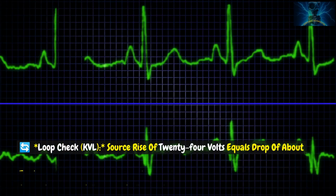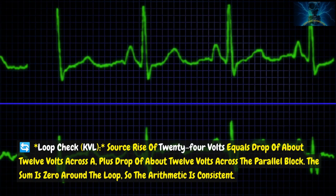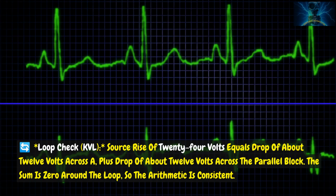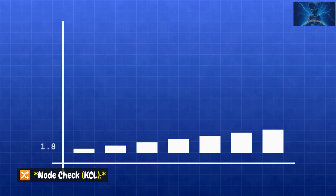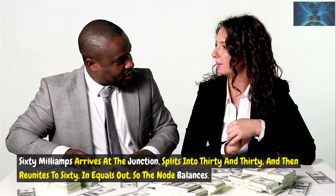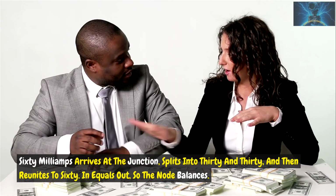Checks that take seconds. Loop check, KVL. Source rise of 24 volts equals drop of about 12 volts across A, plus drop of about 12 volts across the parallel block. The sum is 0 around the loop, so the arithmetic is consistent. Node check, KCL. 60 milliamps arrives at the junction, splits into 30 and 30, and then reunites to 60. In equals out, so the node balances.